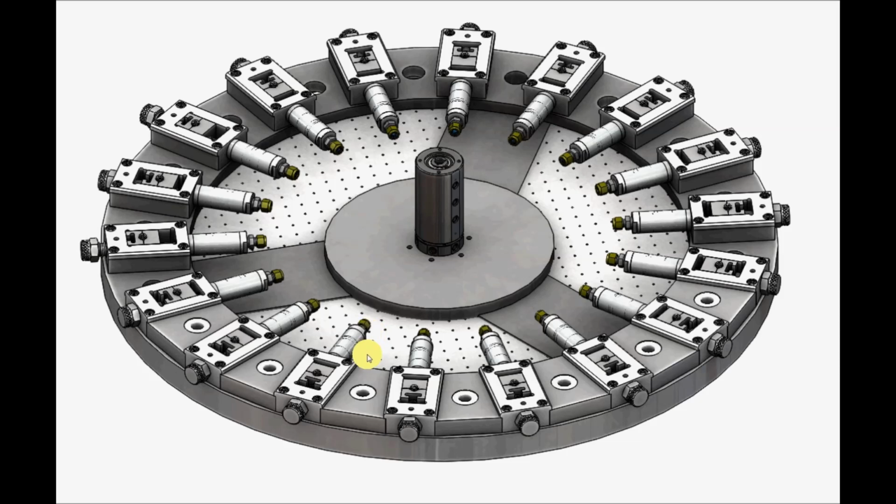And the reason I decided to go with a single acting is because it's a lot more simple and I do not need a real precise motion for clamping. Because think about it, if I use a double acting cylinder, that'd be two ports for each of these. Then I have to bind it to my rotary distributor, which I really don't even have that many ports to begin with. It would have been a cluster. So this is why a single acting made a lot more sense for me in this application.